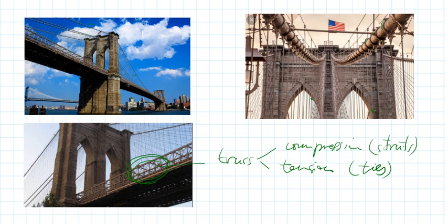We can find also the cables here and here. They are all cables, right? Look how the cables are connected. And this is also quite interesting, that the cables are always at the nodes of this, okay? Just to avoid bending forces. So we are not going to tie a cable here in the middle of the element.